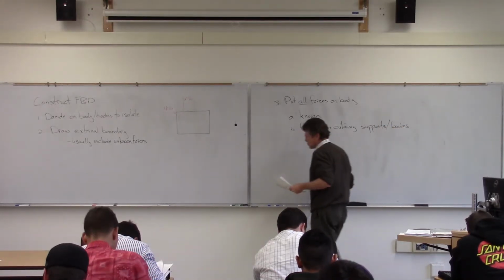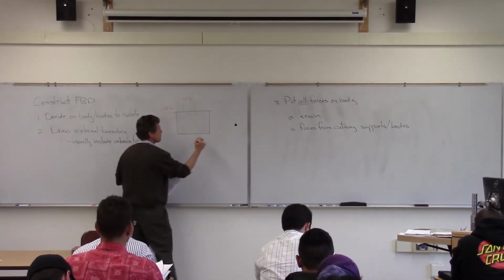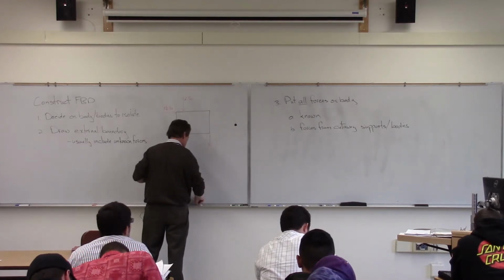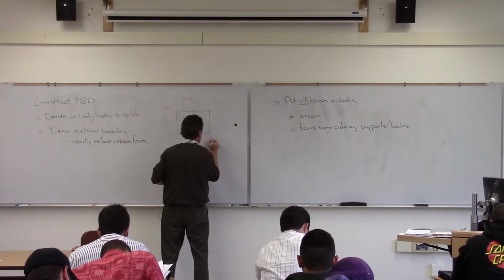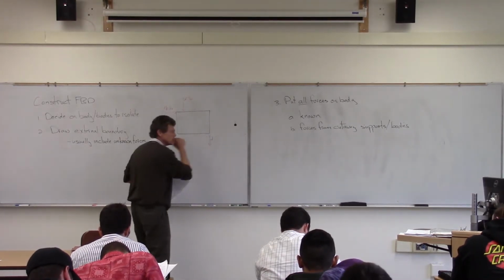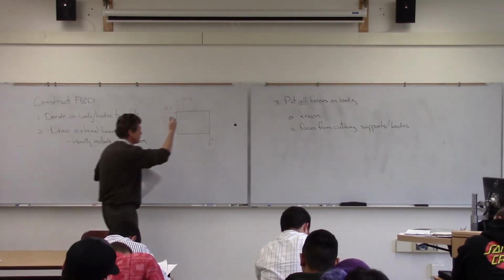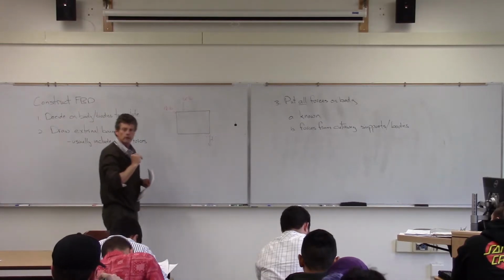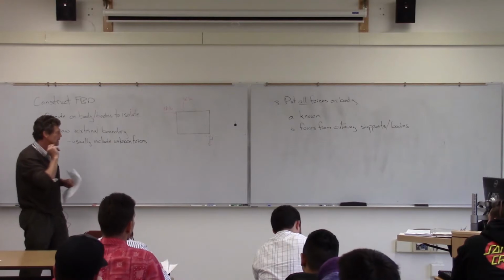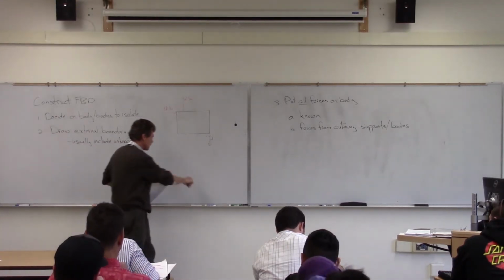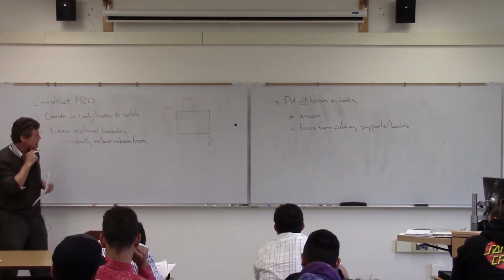Okay, then our next step is those unknowns. Let's get those unknowns in there. So there's a force there at the roller, and again, the roller, I'm going to put in the line of action of that force that's going to be perpendicular to that surface that it's sitting on there. Now, I drew the force probably in a direction that you're all uncomfortable with, but again, I'm drawing that so you have some feel for how statics will self-correct.